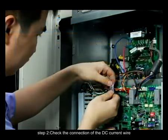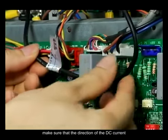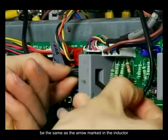Step 2. Check the connection of the DC current wire. Make sure that the direction of the DC current is the same as the arrow marked on the inductor.